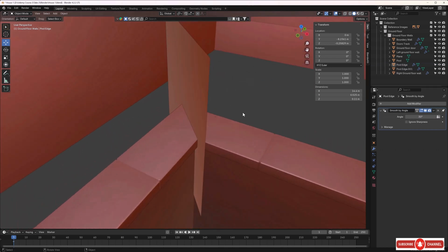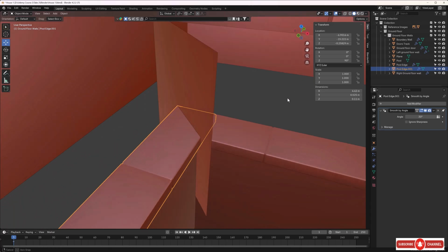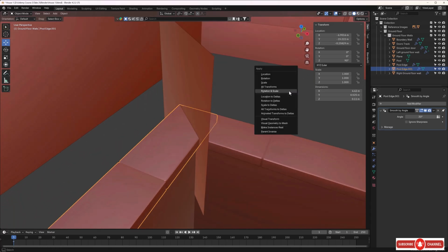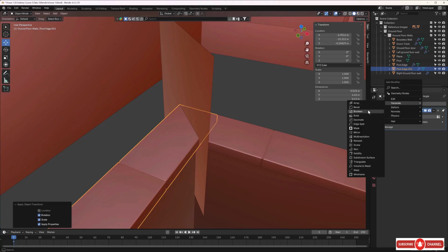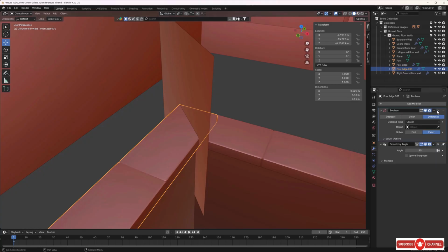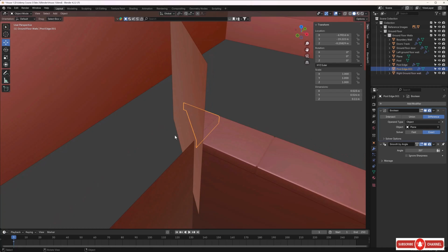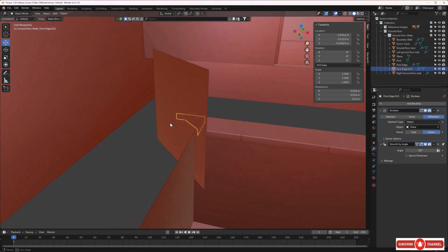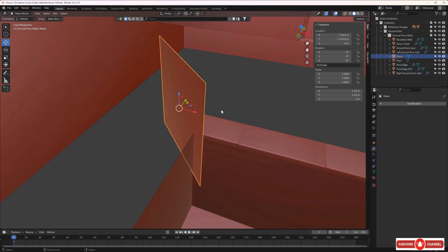Alright, cool. So now we need to do the same with this one. So let's grab this piece here now, check the scales, let's correct those. We'll press Control A and apply rotation and scale, add a modifier and use the Boolean modifier, grab the dropper and click on this one. And we have a problem. It's actually deleted the wrong side for us. There's a reason why it's done that, and it's this cutter that we've got here. The normals on this cutter are facing the wrong way.